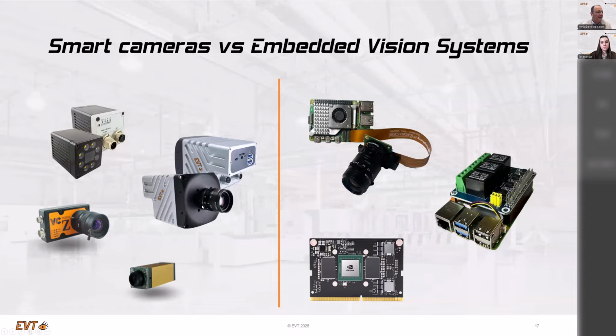Most smart cameras have a C-mount attachment for the lens, as do most of the other cameras which you can buy. Of course, there are some smart cameras with a built-in lens. Then you don't have to buy the lens, but then the smart camera is mostly a little bit more expensive. So at the end, price-wise, there's no advantage. The lens you have to buy separately for the embedded system, but if you compare the two systems including the lens, the embedded system is normally always the cheaper one.